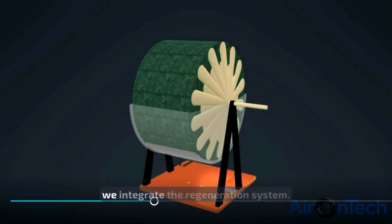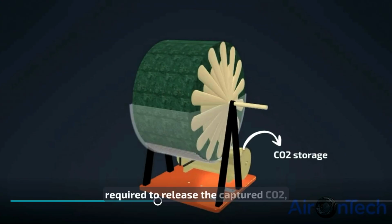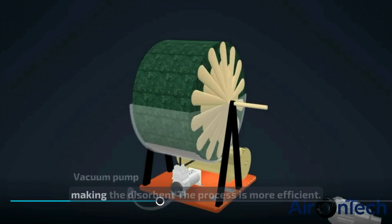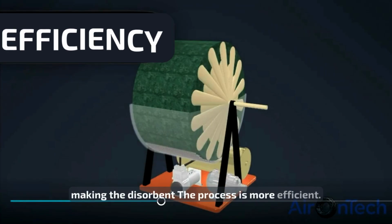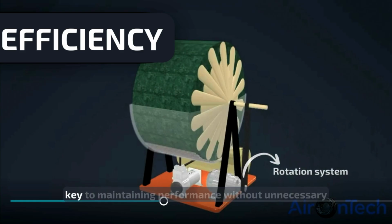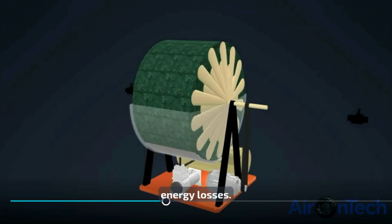In parallel, we integrate the regeneration system. Electric heaters provide the energy required to release the captured CO2, while vacuum pumps reduce pressure, making the desorption process more efficient. The synchronization of these elements is key to maintaining performance without unnecessary energy losses.